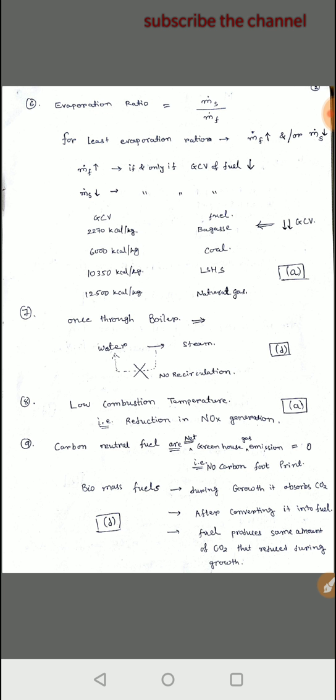For least evaporation ratio, from the equation we can conclude that if mass flow rate of fuel is increasing and mass flow rate of steam is decreasing, then and only then we will get least evaporation ratio. For increasing mass flow rate of fuel, GCV of fuel should be lowered, and to decrease mass flow rate of steam generated, we also require less GCV of fuel.